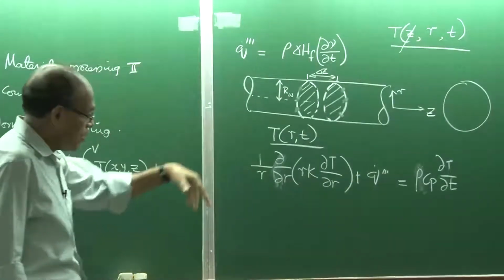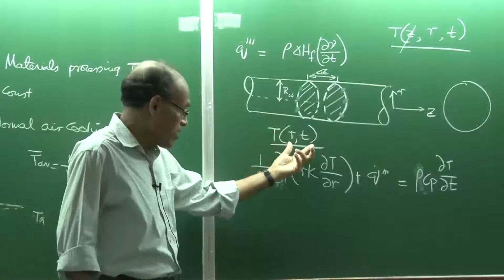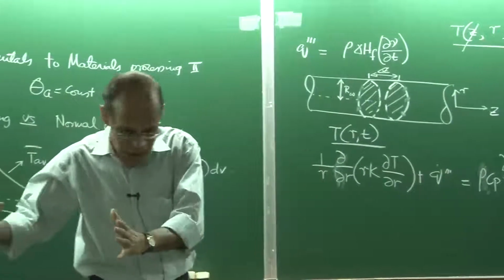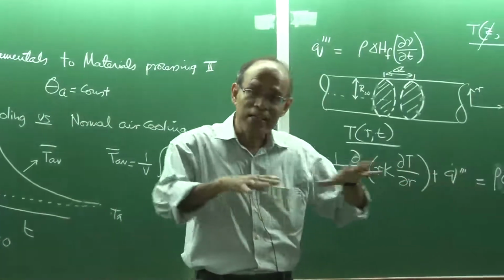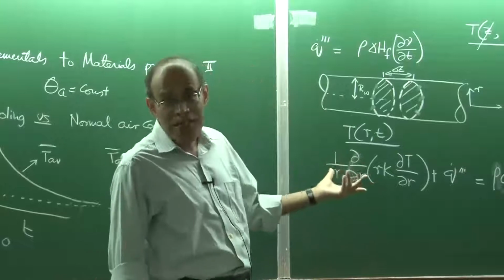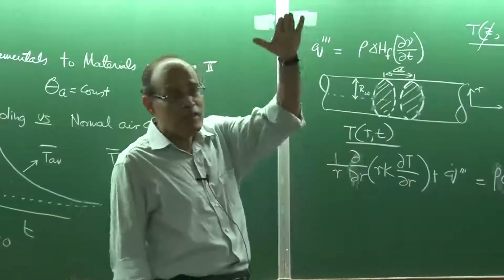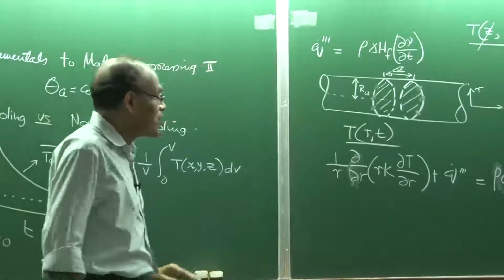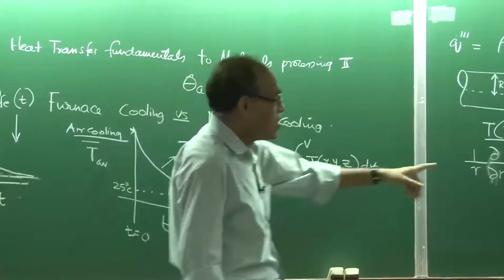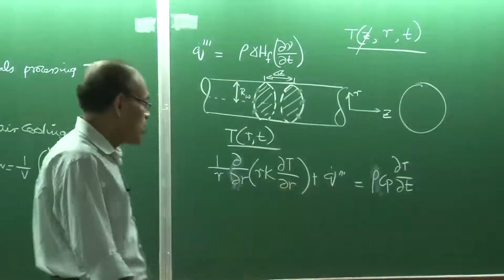So, the variation of temperature within the wire as a function of time, as the homogeneous piece of wire is brought out and subjected to forced air cooling, then solid state phase transformation reactions start. As the temperature goes down below the AC3 temperature, austenite will get transformed into pearlite, and so there is a change in the volume fraction from austenite to ferrite.